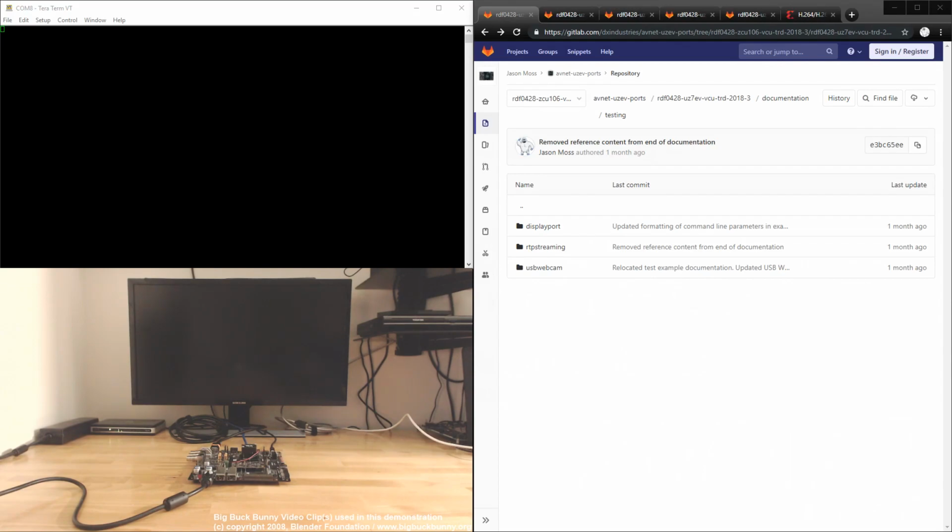I'll highlight that even though this is a 4K display, you're going to see in the demo that it only supports 1920 by 1080, and that's because the DisplayPort itself on the I/O carrier card only has a single serial lane running to it. And at HBR2 high bitrate 2 mode for DisplayPort, that can only support up to 1920 by 1200 resolution at 60 frames a second.